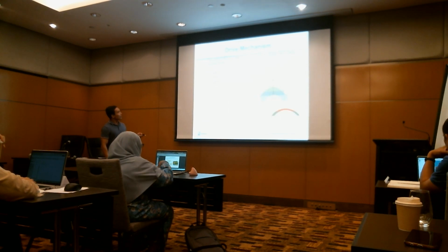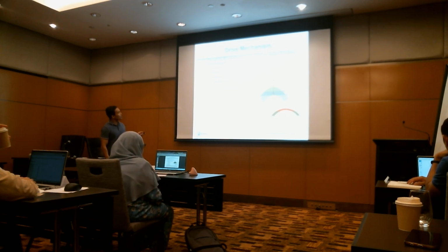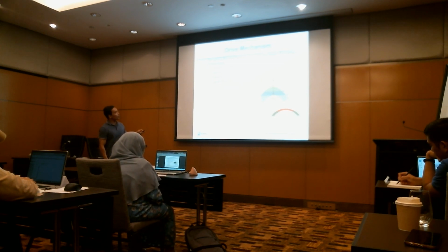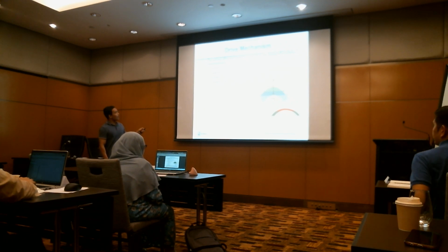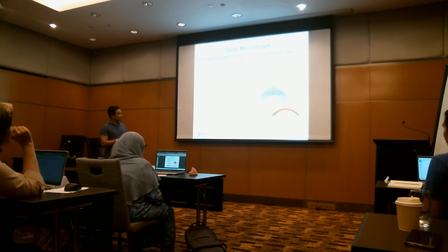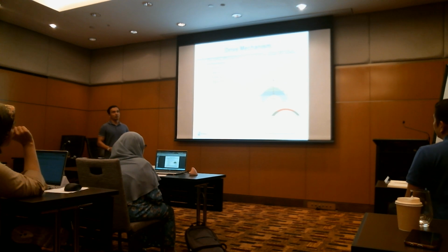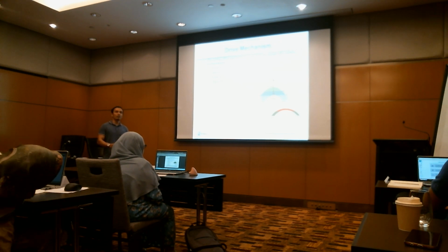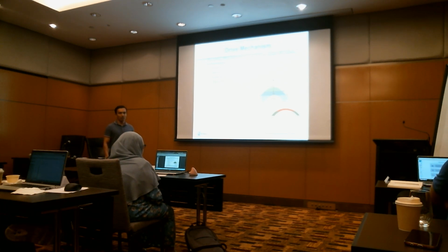There are various drive mechanisms that come from the impact of a number of phenomena. For example, the first one, expansion of reservoir fluids: oil, gas and water. In the fluid itself, you have compressibility. In the reservoir equation, starting with G, there is a Bg and Bo element, which is an expansion factor. So the fluid itself will expand as you produce from the reservoir, and that gives energy to the reservoir.